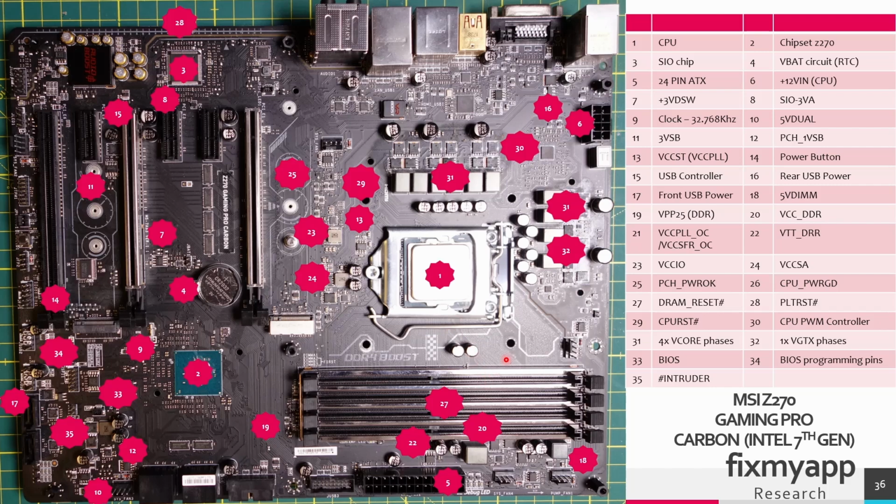For that I will use this 7th gen Intel motherboard. I will provide information about the BIOS, the voltage regulators, the ATX power supply, the Super I/O chip, the platform controller hub, also known as the chipset, the different voltage rails that are on the motherboard, how a logic AND gate chip works, and the VRMs that generate the VCore voltage for the CPU. I will also provide information about the TPM headers and which tools you can use to troubleshoot a mainboard.